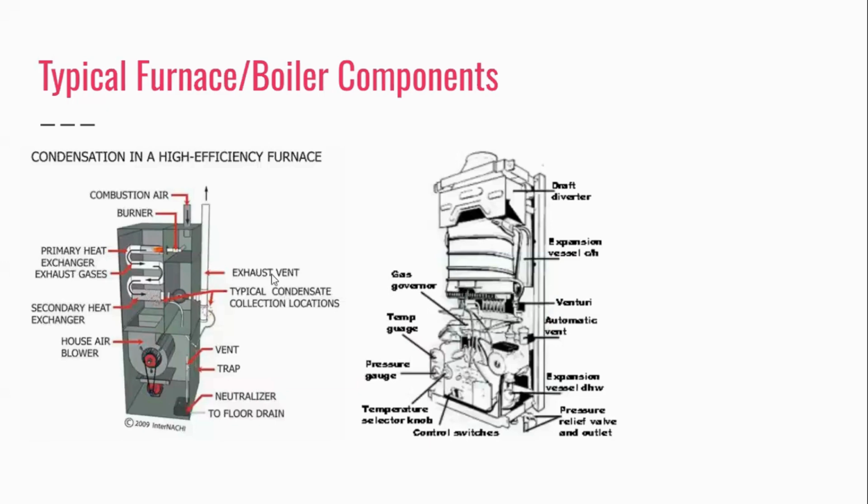Then we have our exhaust, another super important thing on both boilers and furnaces. If your exhaust, if your flues are not clear, you will have all kinds of issues that will tell you that they're airflow. They'll tell you that your heat exchanger is cracked. They'll tell you it's dirty. They'll tell you all kinds of things when really all it is, is a mama bird making her nest in this exhaust vent. Always check your exhaust vents on maintenance. Make sure that you do. And that, again, goes for boilers and furnaces.